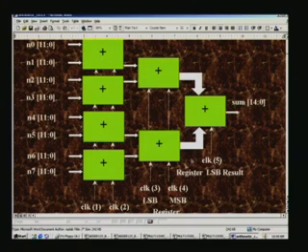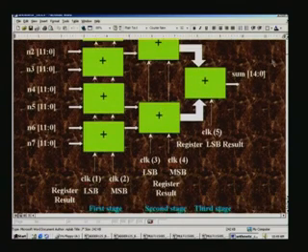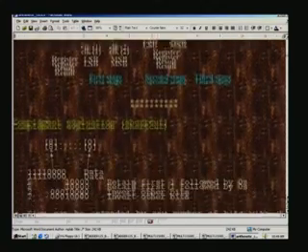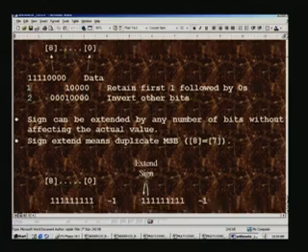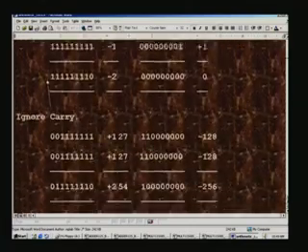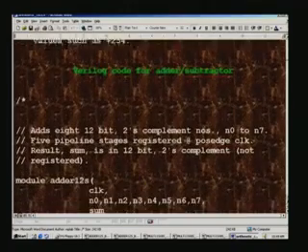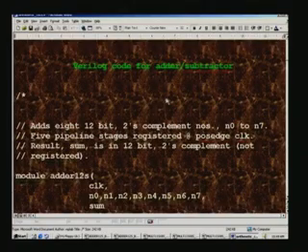And we had 3 stages of pipelining here, with 5 internal registers used as pipeline registers. Note that the last sum is not registered, and we had seen how to take a 2's complement of a signed number, and these were the examples we had considered earlier. And now let us have a look at the Verilog code for this adder subtractor.